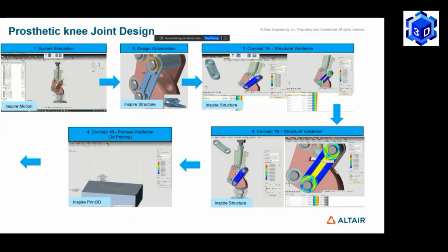However, the other part of the hip joint is the femoral stem. That is where the FEA, finite element analysis, is very important, because it's the head and the neck of the femur where the joint reaction forces are maximum. So when you design an implant, you need to understand that the lattice strength is the maximum in the area where the maximum load bearing is going to transfer. Correct. So you can do an FEA.